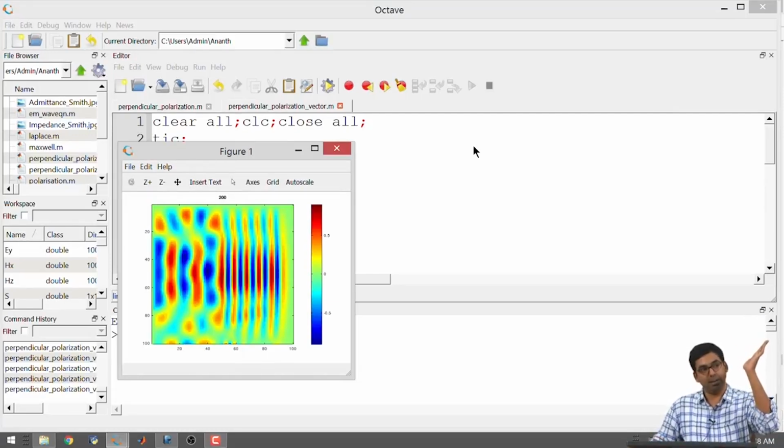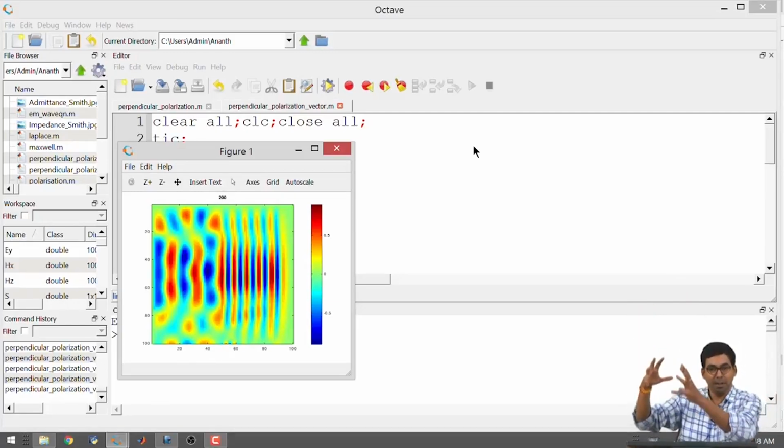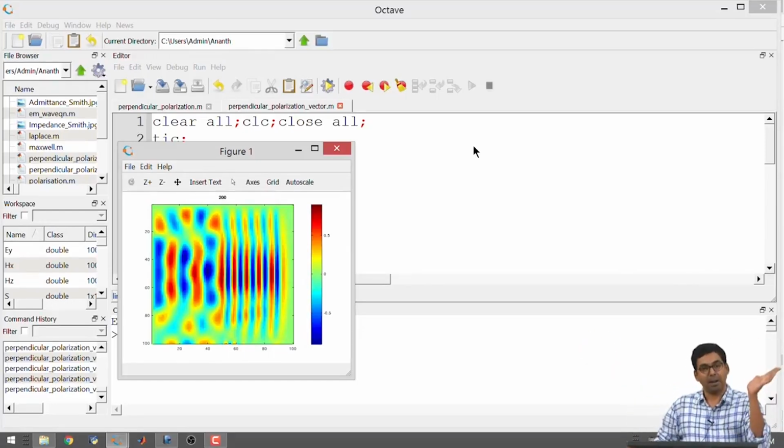So you can always start at 0, doesn't matter. And then you will calculate x going from 1 to 25, y will be equal to m times x. You will create one vector over there, then you will take Ey at these positions x comma y is equal to 1. Then you can create some slanted source, you can control the angle, all that. So you can do that, you will be able to observe total internal reflection, etc.